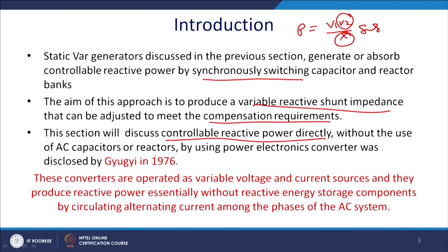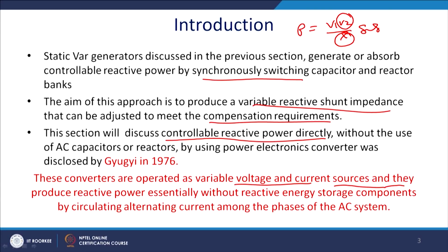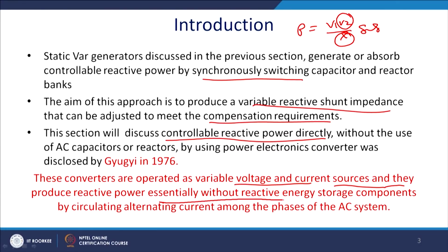without the use of extra capacitors or reactors, by using a power electronics converter as discussed by Gyugi, the famous writer, along with Hingorani, of the famous book on FACTS devices. This converter is operated as a voltage source, current control inverter or converter. Voltage source, current control inverters produce reactive power essentially without any storage of reactive elements. So, inductors and capacitors will not be there; that is one of the basic advantages of this STATCOM. It works essentially without effective energy storage components, by circulating alternating current along the phase of the AC system. So, it will be dynamically controlled and it will be faster in action than the SVC,